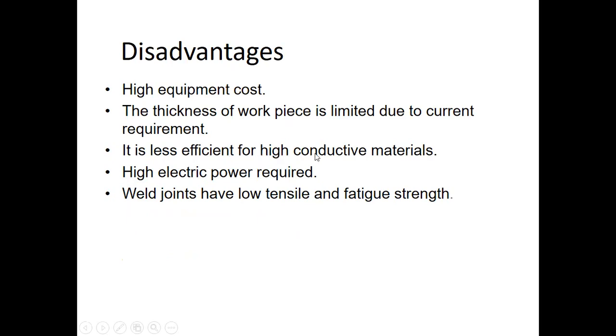It is less efficient for highly conductive materials, because if the material is conducting, then there will be no resistance, or lesser resistance. This is a major point. For conductive materials, resistance welding will not perform as you intended, but for less conductive materials, this is one of the best processes.